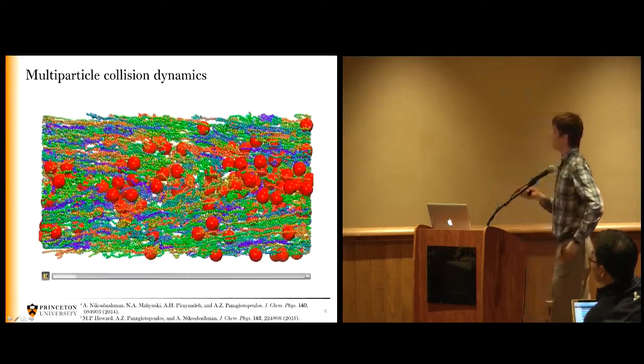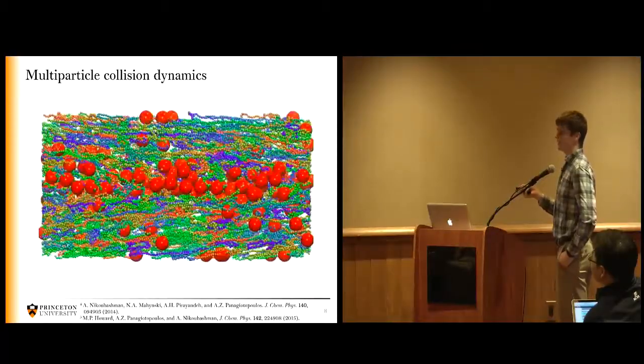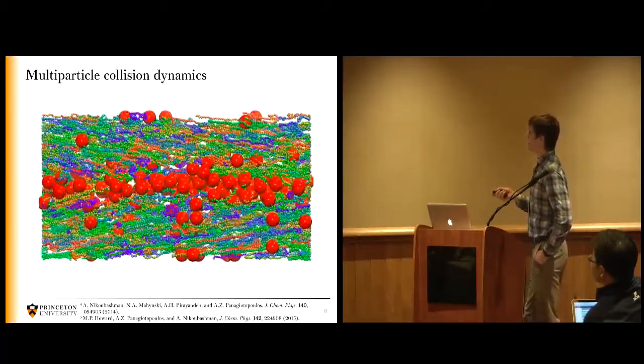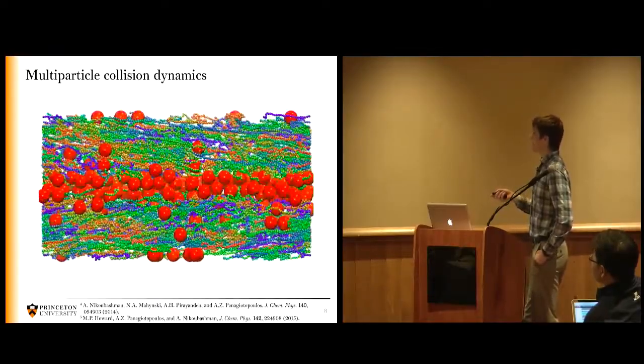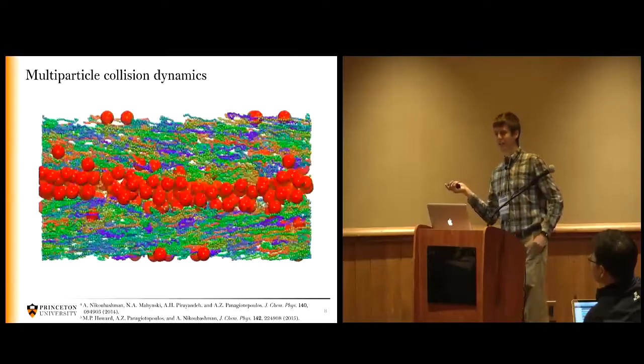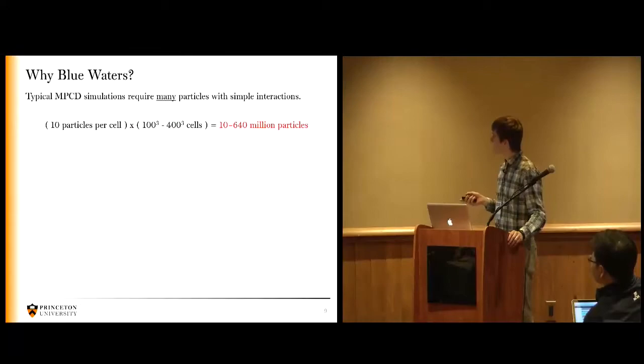And so you can see as the simulation goes, we get this interesting effect for the polymers, which we would expect, where they're stretched out by the flow due to the shear rate in the simulations. And also we observe the migration of the colloids into the center of the channel, which is a very interesting focusing effect that we were interested in for particle sorting or cell sorting.